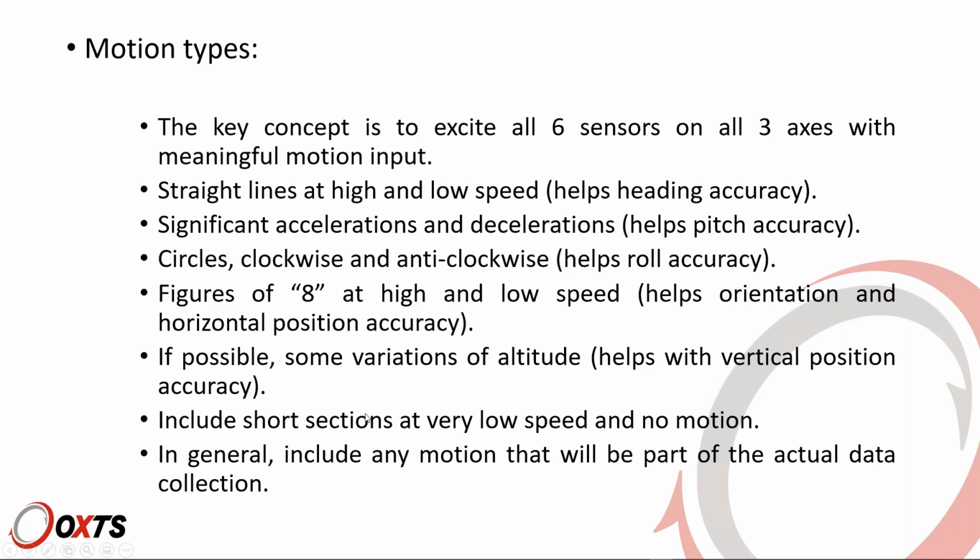If you know that you are going to stop a lot, for example, at traffic lights, then try to include some of that in the warm-up. Stop 30 seconds, and then move again, then stop 30 seconds, then move again. Try to include as much as possible whatever motion you know you're going to have during your data collection into the warm-up, so the system learns about it. And again, do the warm-up in an open sky environment. Once you have done the warm-up, you can go into dense urban environments, but only after you have completed the warm-up.